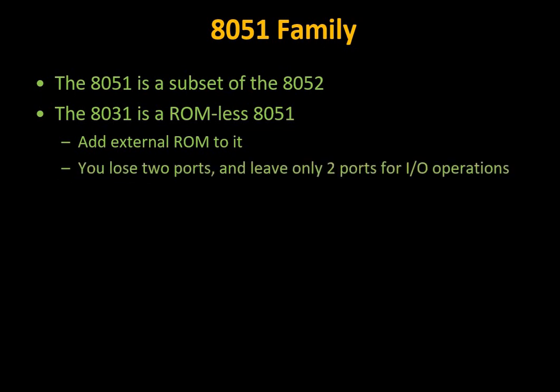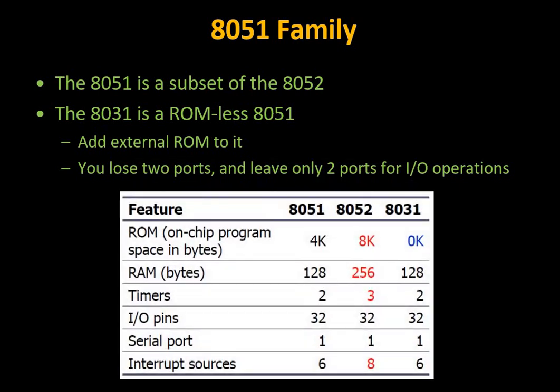Also the 8031 is a ROM-less 8051, to which you add external ROM. Also you can lose 2 ports and leave only 2 ports for input output operation.